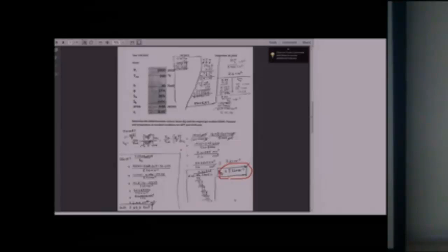Okay, P_SC over P times Z times T over T_SC. You should be able to derive it, just like we did when we first did that one homework problem with the cylinder, and we calculated Z's. We have to know the fundamentals of the real gas law. So calculating a gas formation volume factor represents the ability to understand the real gas law.